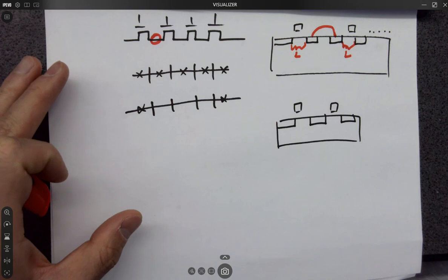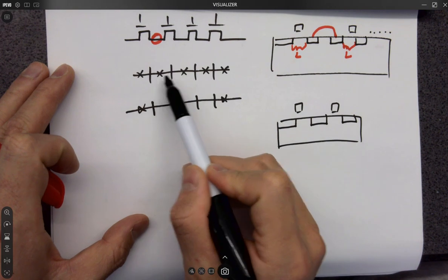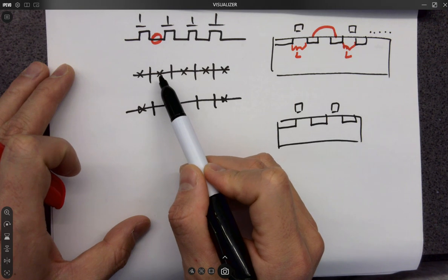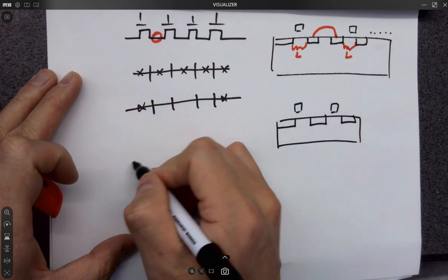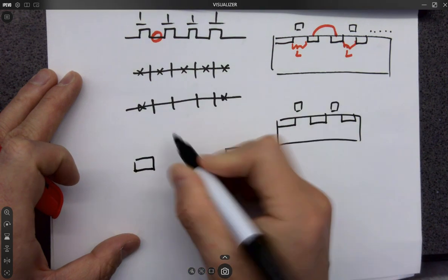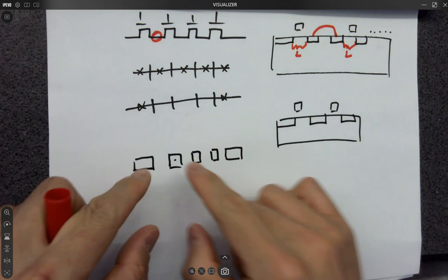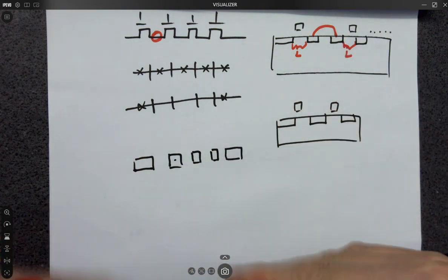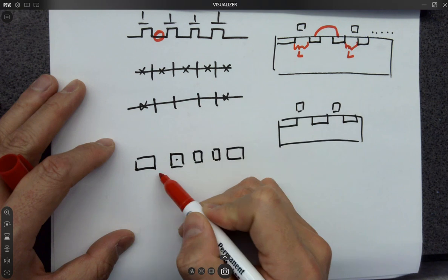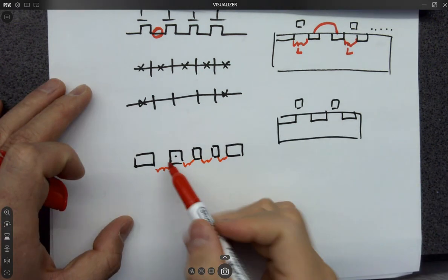So in between, what's happening is it still has the diffusion, but doesn't have the via and nodes, the metal one on the top of the via. Okay, so what's really happening here is you do have, for the layout top view, for example, right? It's separating all these areas by this diffusion, but there's no via and node and metal one on the top. But there's still diffusion in there, like P plus or N plus. But it's being separated by all these diffusion blocks and only leaves all these separate channels in there. So they are getting all these lengths added together in series. That's what's happening. Okay, that's why the length is not changing. It's just adding all this length together.